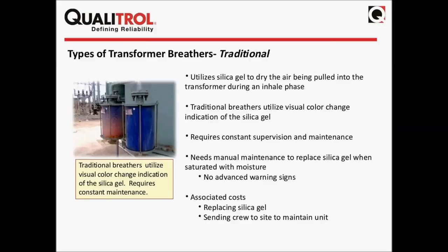And of course, there are associated costs with this, because you have to replace the silica gel generally every 3 to 6 months. Again, it depends on the region of the world. Sometimes they last more like a year and a half. It really depends where you're located and how much water is in that atmosphere. And you also have to send a crew out to the site to maintain the unit. So they have to dispose of the silica gel, get rid of it. Sometimes there's environmental concerns associated with that, depending on what type of silica gel is inside of there.